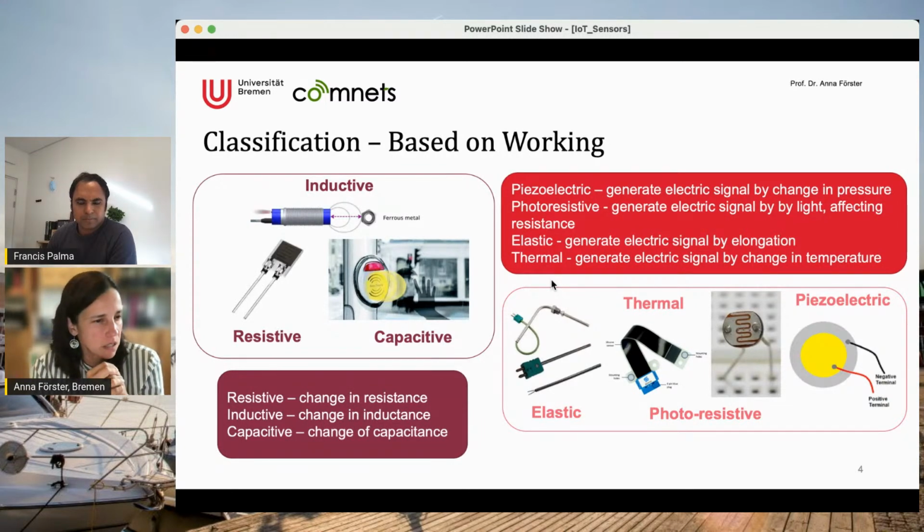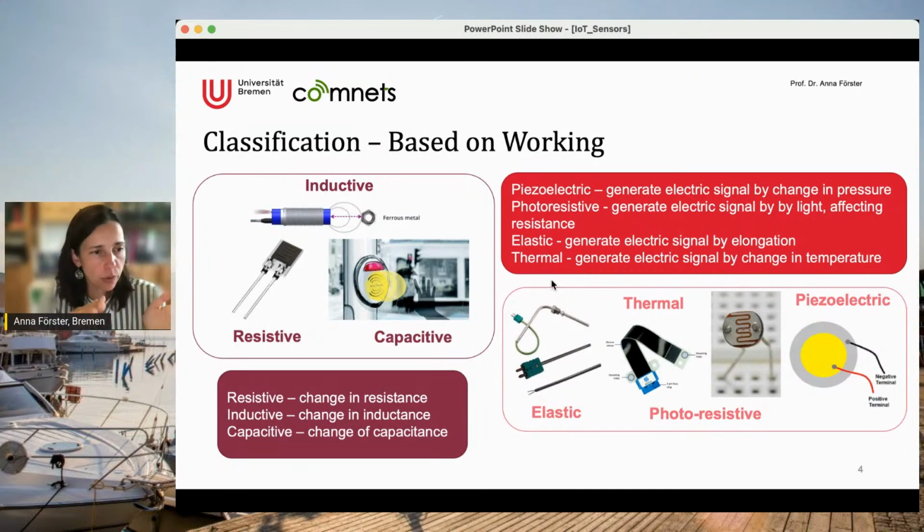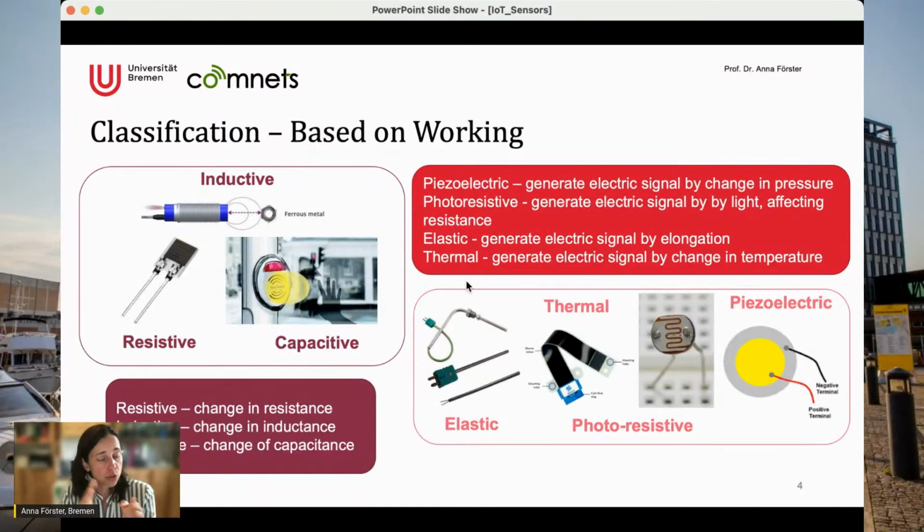It is not necessarily important that you actually know how your sensor is working. What is much more important is to understand that you have to read the specifications very exactly. What is normal is that a particular sensor will work well in room temperatures with some sort of humidity of the air, and that it will also have some sort of a spectrum. For example, the temperature sensor will give you good information between minus 20 and 20 degrees, but you should not count on it whenever it starts getting really hot, or really cold.